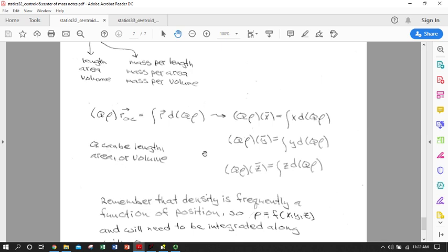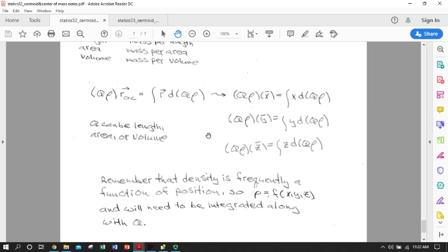For instance, maybe you have more on an outer circumference of a beam or a rod to give it better moment resistance. You would then be looking at maybe having a higher density closer to the max tensile axis, depending on what you used. Anyone who's familiar with soils and compaction will know that quite often you'll get gradient density if you have settling or differential void volume in soils. So that's another place that you might use a gradient density function. All kinds of things can lead to different densities.